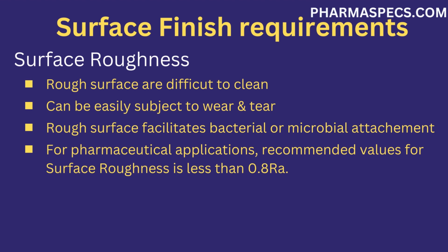Rough surfaces are difficult to clean because uneven surfaces facilitate the deposition of foreign bodies and contamination in them. These foreign bodies cannot be seen by the naked eye. Rough surfaces can be easily subject to wear and tear because they have a low tendency to attach with the primary material.